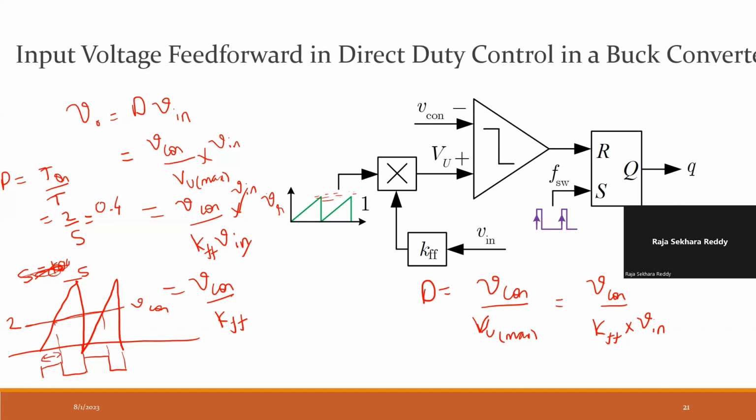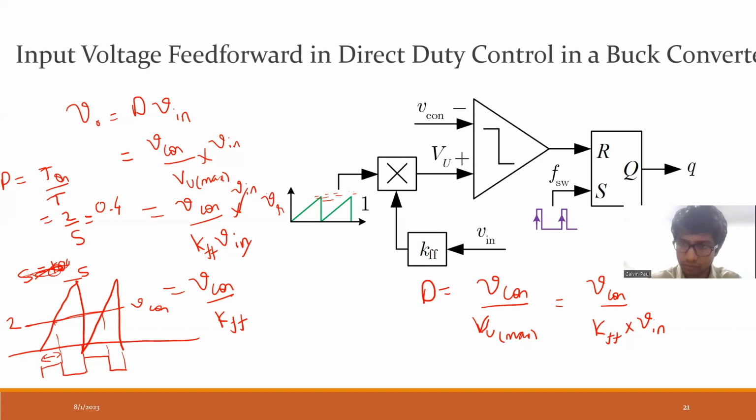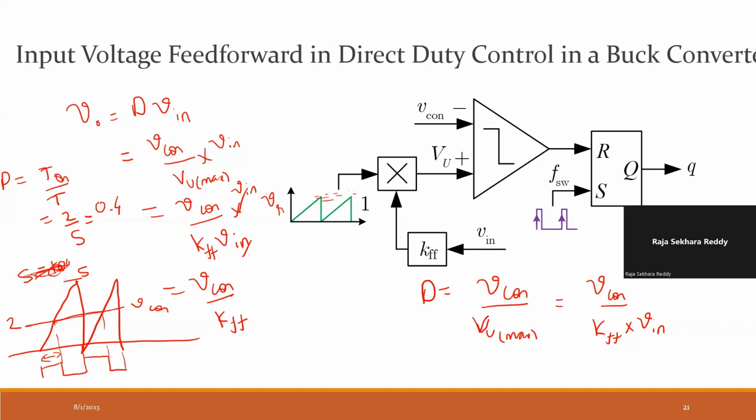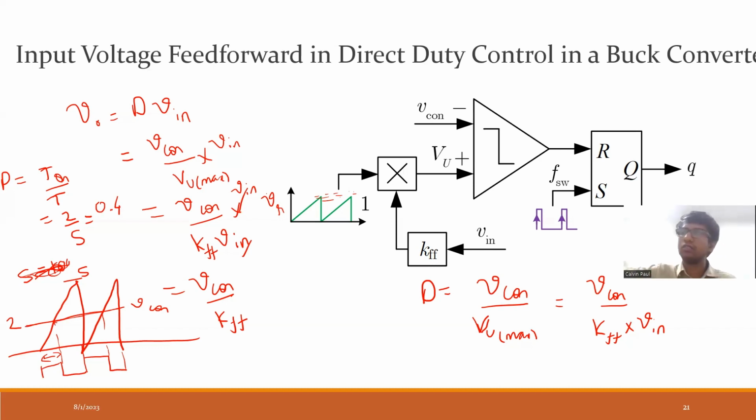So programming that microcontroller, STM board and that Texas board, which kind of software do we need to learn for that? See, ST microcontroller boards have CubeMX software to configure the microcontroller, and then they use IAR Embedded Workbench to write the code, etc. TI uses Code Composer Studio or something, and other stuff. Those softwares are available on the website if you check. Those are freeware softwares.